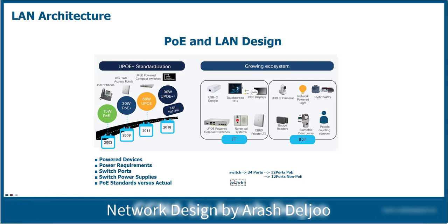The port of this switch can supply the 15 watts, but our device, our PD, only needs 7 watts. It's okay. We can apply less than the maximum available power on one port. And with the negotiation with CDP and LLDP, the switch can find which amount of power is suitable for the device. This negotiation occurs over time. If the requirement changes, again we may apply another amount of power over Ethernet.